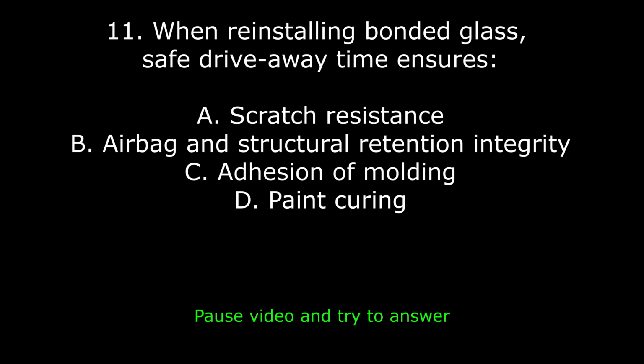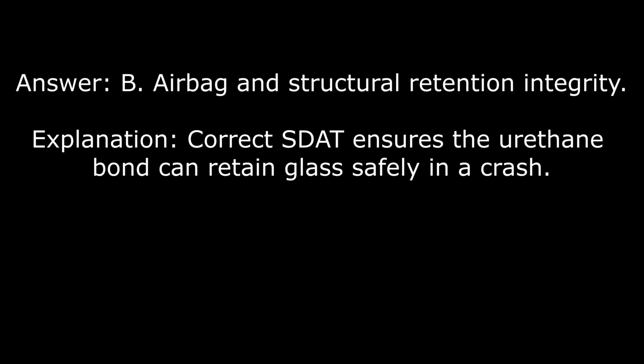11. When reinstalling bonded glass, safe drive-away time ensures A. Scratch resistance. B. Airbag and structural retention integrity. C. Adhesion of molding. D. Paint curing. Answer: B. Airbag and structural retention integrity. Explanation: correct SDAT ensures the urethane bond can retain glass safely in a crash.